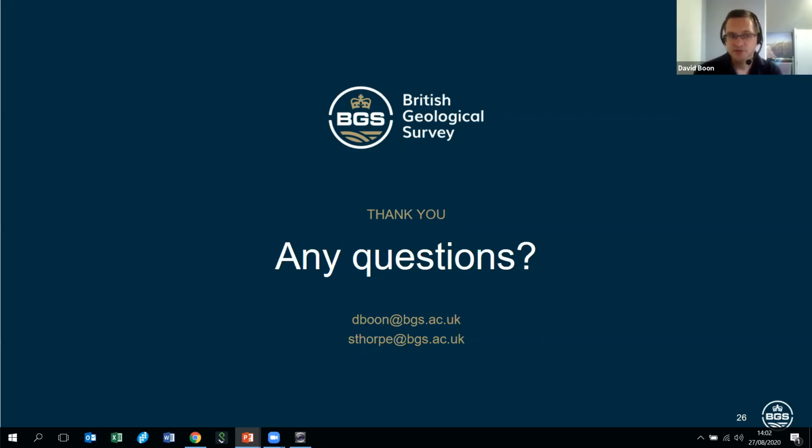It's a very useful starting point if it's a small project and you can't afford a TRT test. It's part of the information your designer will use to make some judgments about how the ground will perform. If you've got groundwater flow going through the site, the estimated values that we provide in our GeoReports will be an underestimate. They'll probably be a conservative estimate generally of how the ground behaves, so you might usually expect even better performance than the estimated values we provide. So always get an expert on board early on, get a geologist on board early in your project, and you'll have a successful project.